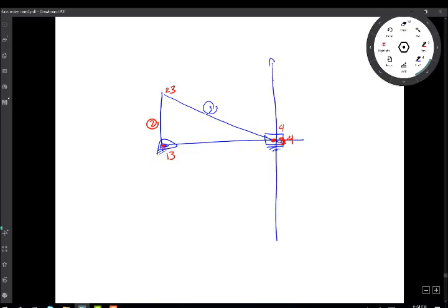So this will be 4, 1 at infinity, because 4 slides on 1. So that's just a pivot. Okay. Now, this is perpendicular as well. So this is the thing I'm drawing here. This is R2, that's perpendicular. So now if I want to find 1, 3, this will be the locus for 1, 3, because I have the two numbers.